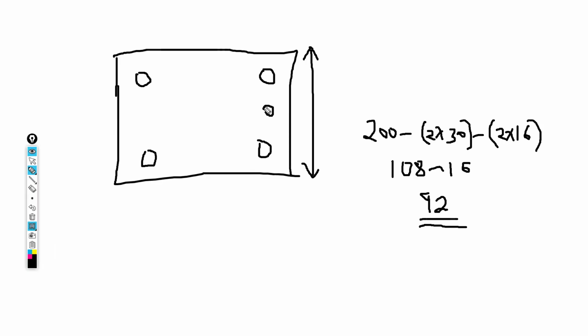Reason being, if you alter those preferences, you're going to end up with very small spaces and your maximum aggregate size might interfere with the design constraints. You get it? That's when you find issues of segregation on site, if bars are closely packed.